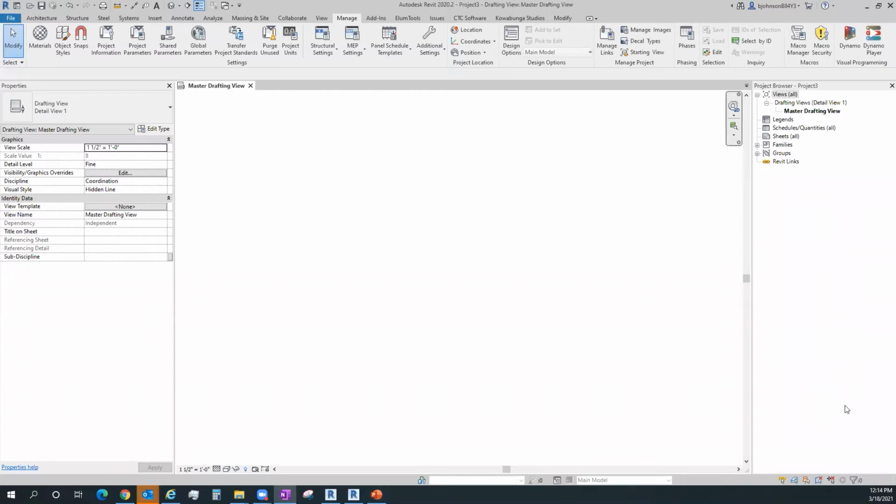All right, so anything AutoCAD based that you need to do as prep, again, you're going to have to kind of find your way through the process the first couple times you do the detail conversion if you've never done it before, just to make sure that the things you're getting from CAD are going to translate well into Revit. Once you've done that a few times and know what to expect, that's when you can go back into your CAD files and do great things with them. Again, you could create the M text a regular text entity, but a lot of times those objects will have really stretched out windows of text, and to go back and fix those is not my most favorite thing.